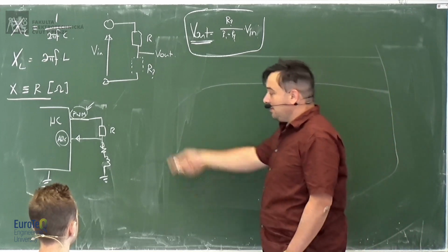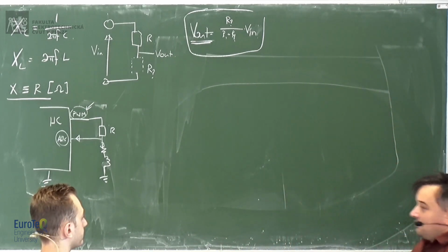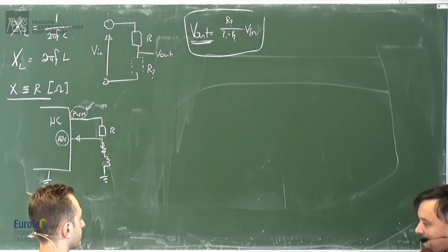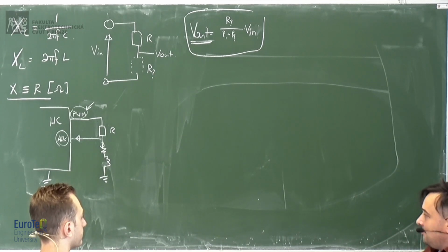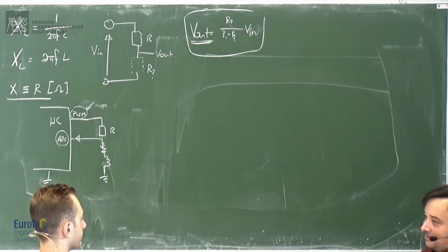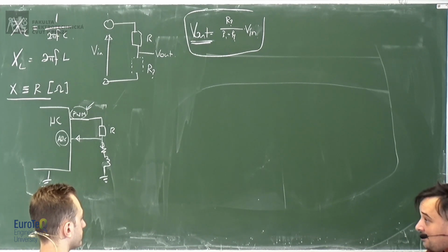One of the problems: you say, okay, I use a frequency where I go up and I consider the resistance negligible. If I use a frequency where the resistance becomes negligible compared to the reactance, I can forget about that, which is one approach. But the reason why I said it works to some extent is because it depends on how precise you want to be. If you don't need to be very precise, everything is okay. You can say, I go up to a frequency where the resistance becomes negligible, and who cares if I have some resistance there. But you should remember that the resistance changes with frequency as well. The impedance changes with frequency itself.